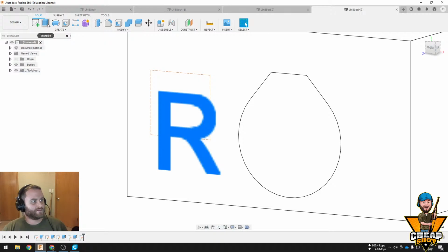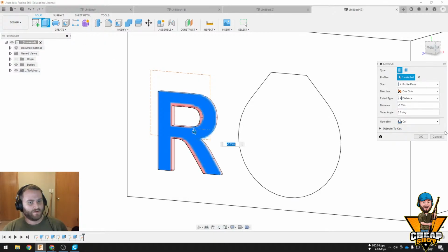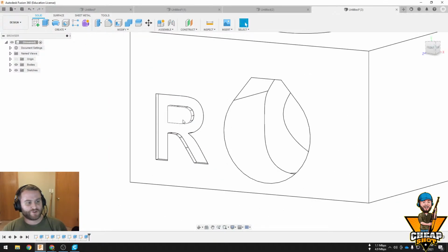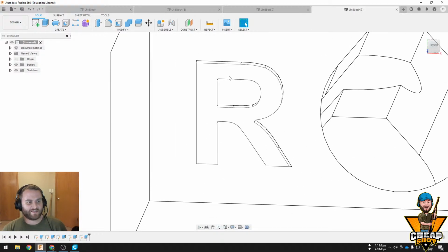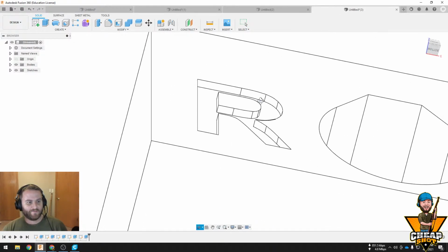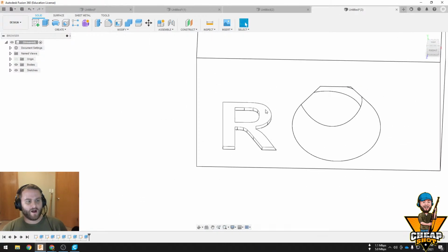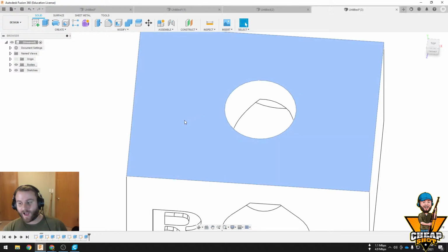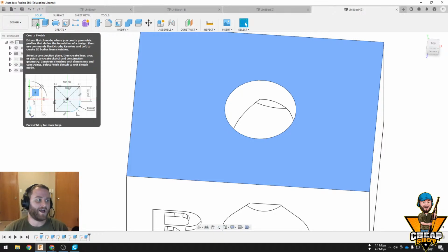If you really want to make it stand out, you can Sharpie in there or something. That R will print okay, but if I were to bring it out, it wouldn't really work. On the top, you can do it. One thing you need to be aware of is your infill. Infill doesn't really work for support, but it will support that top layer.